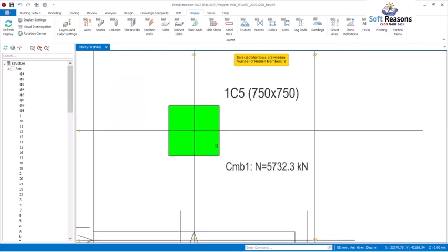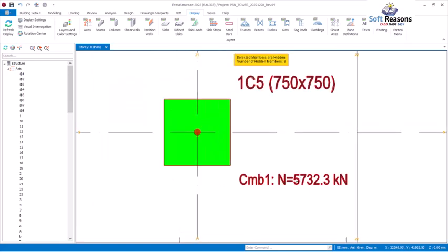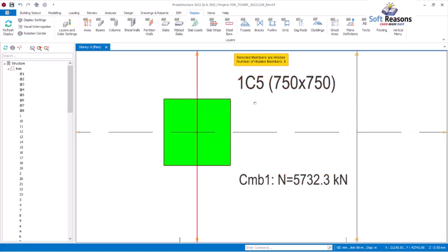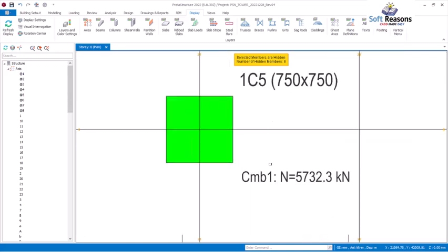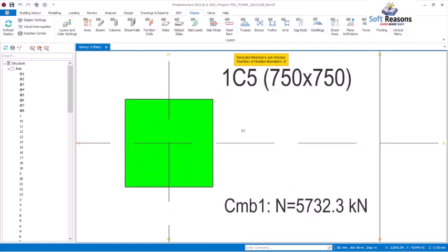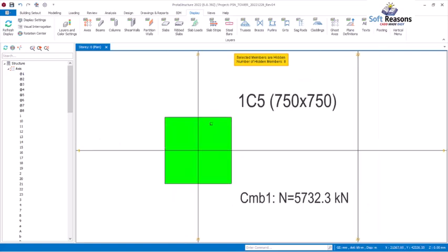Having answered that this is an ultimate load, where do we find the service load? Before we go into looking for where we can see the service load that we use to actually design the member that can carry this column, it could be pile foundations for the sake of this kind of high-rise structure, because this is up to about 10 floors thereabout. So now we have to understand the difference between ultimate and service load successfully.